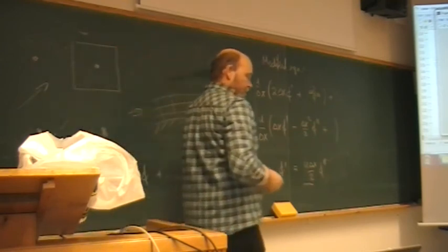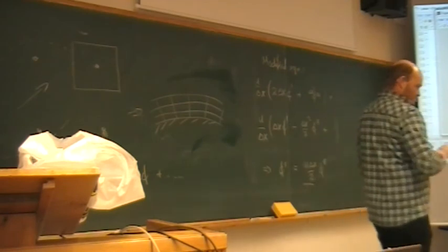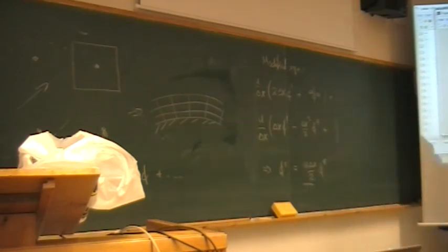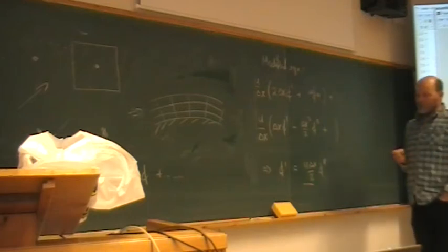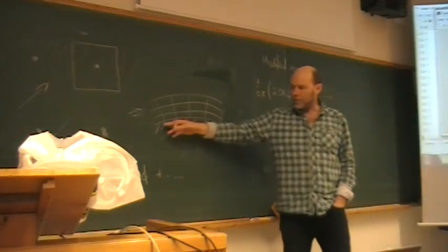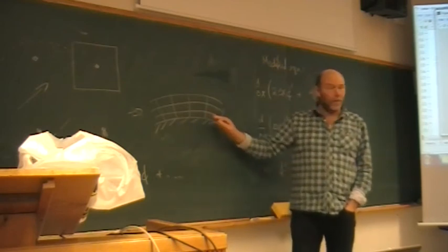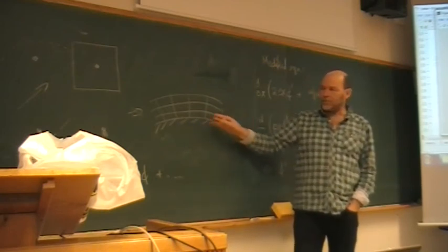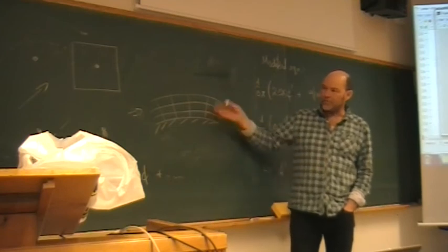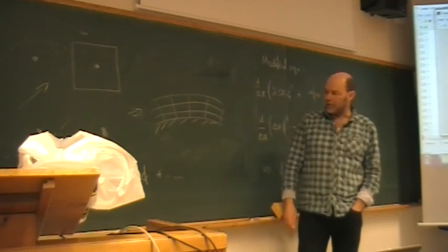Maybe not so many layers, 4, 5, 6, up to 10. Just to resolve the boundary layer, because a lot of physics is happening very close to the wall. Here you have the skin friction, the production of turbulence is happening down here. Very important to resolve this one correctly to get lift and drag forces on an airfoil, for instance.